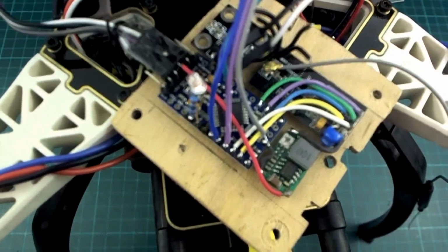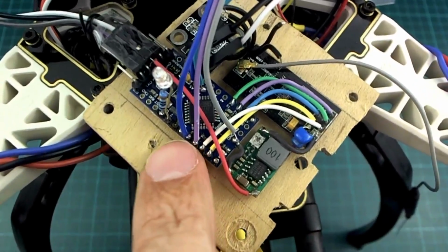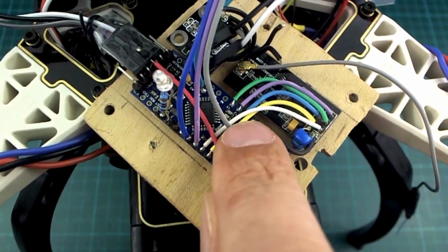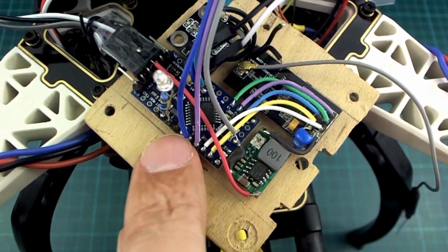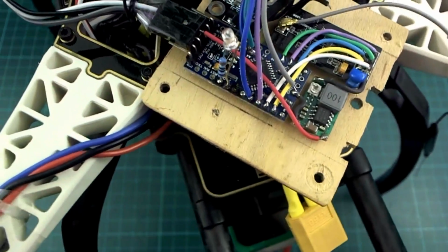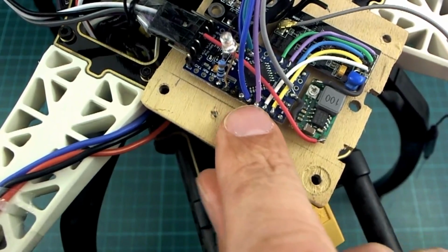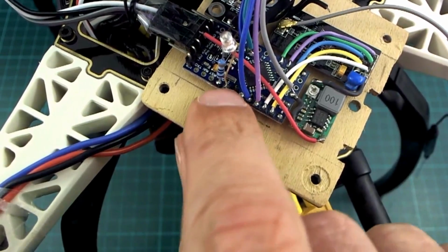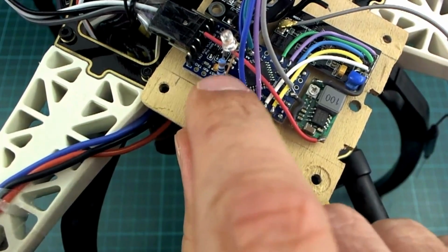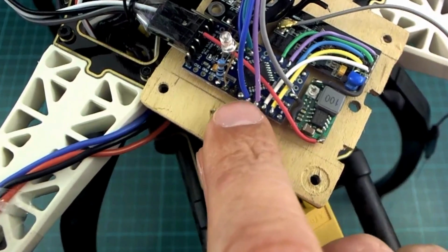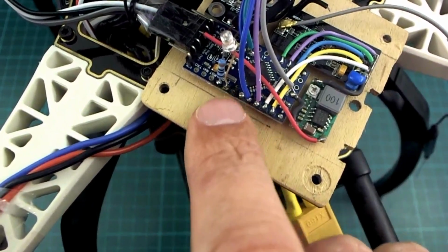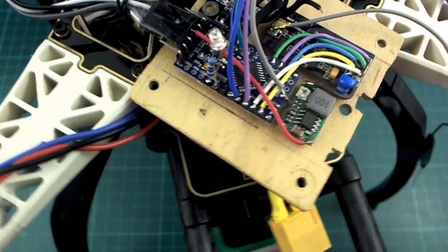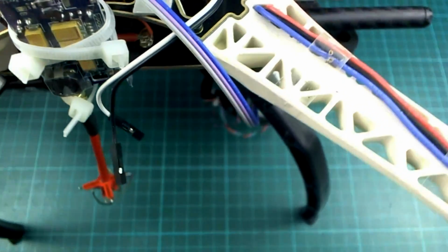So that's that one, and then there are 3 other wires here. This one's coming from ground, and these 2 are coming from, in my case, pins 5 and 6. I preferred to have them on 3 and 5 because these are the faster PWM outputs, but my pin 3 is going a bit strange. I can't solder onto it properly. It just doesn't take solder. So I'm using pins 5 and 6, but I've made the sketch to use 3 and 5. And if we follow those over, the blue and the purple one go all the way around here.